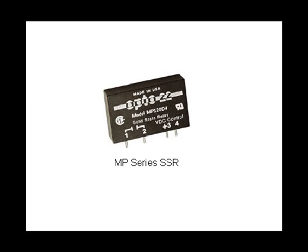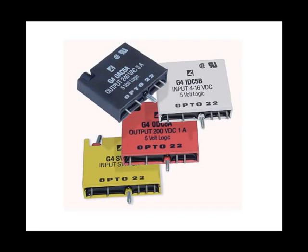Here is an example of several variations of solid state relays. The black module is controlled with 5 volts DC logic and will switch up to 3 amps at 240 volts AC. The white module converts a DC input signal in the 4 to 16 volts DC range to the 5 volt DC level used by the controller board.